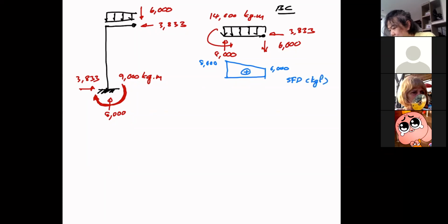And the bending moment diagram, if you start from the left, this is counterclockwise on the left, so it's a negative of minus 14,000, and with the positive shear area, it goes back to 0. Kilogram meter. And the last piece, may I look at it from this direction?